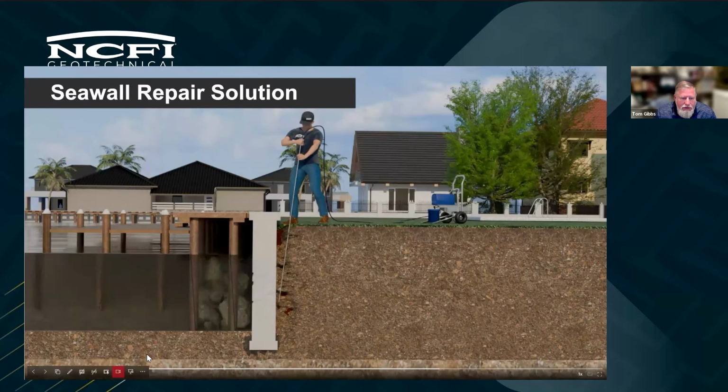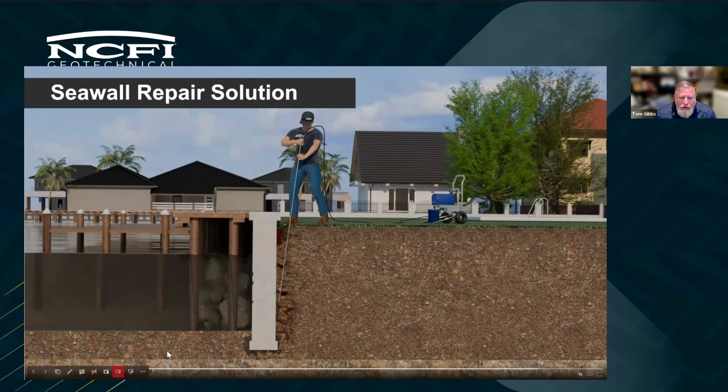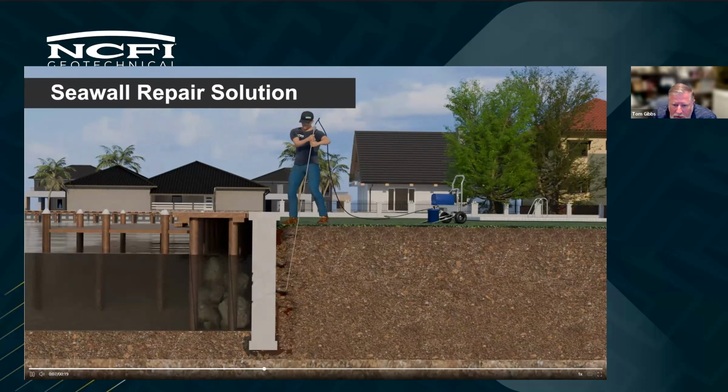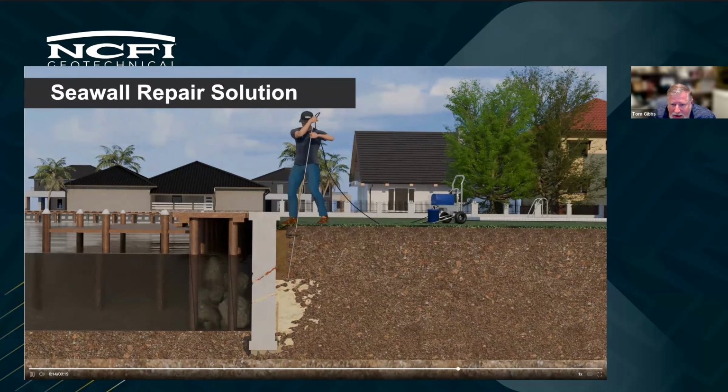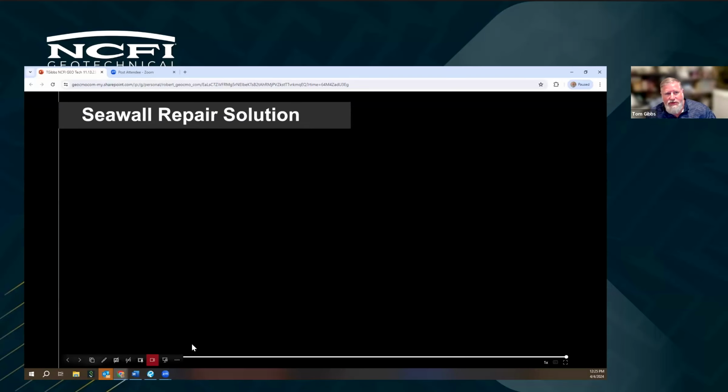Quick video here. Thanks. So this kind of shows using a single component pump to grout the grounds behind the seawall there. Typically, what's going to happen here is you're going to have some expansion into the soils that's going to help to push the soils out, so you've got good soil that you're grouting.